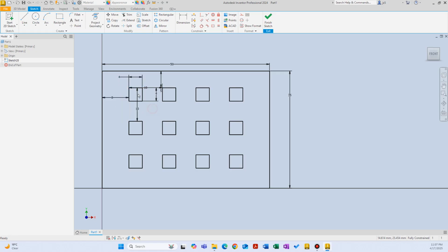Okay, so the way it created the pattern is it's 10 millimeter apart, and 10 millimeter is measured from the horizontal line on the top to the horizontal line of the top for the next square. And again, it is the same square 4 by 4, and it's 10 millimeter apart. And I didn't have to create this one by one. It took me seconds instead of minutes. So you can create this design using the rectangular pattern.